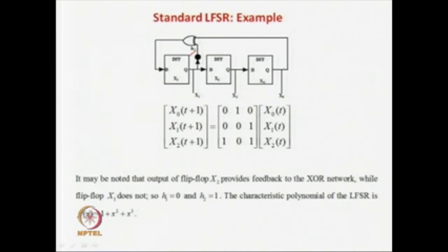Now, what will be the matrix? You know that this is a diagonal matrix. For this column, the last bit will be 1. Why is this last bit 1? Because we always know that x0 must give a feedback to the first flip-flop. So, this has to be kept as a 1, because to generate x2, this is multiplied by this factor, so we always get the feedback. This implies that x2 at t plus 1 will be determined by x0. This is the minimum thing that is required.